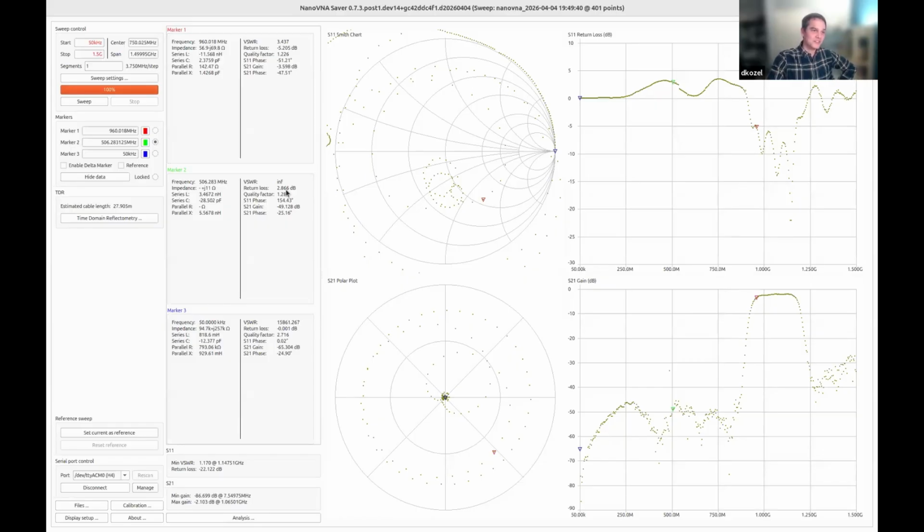If you operate outside of their pass bands, a lot of the time they're reflective and will send the power straight back to your radio, being a terrible SWR. Now this is being smart enough not to try expressing this as VSWR, which I don't know why. You should still get a value for that. But yeah, the power will come right back at you, and that can be deeply inconvenient.